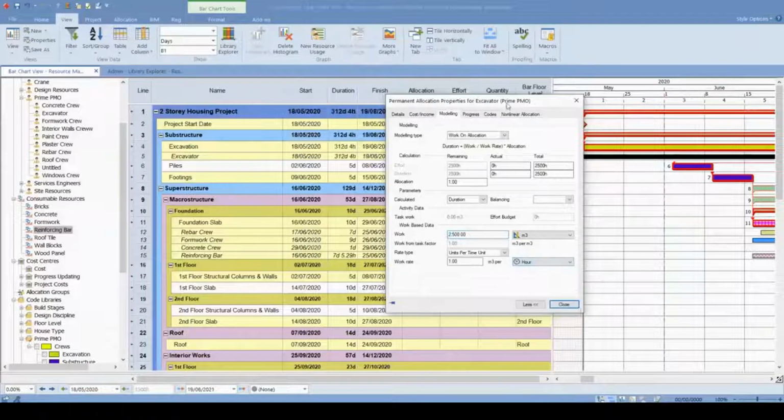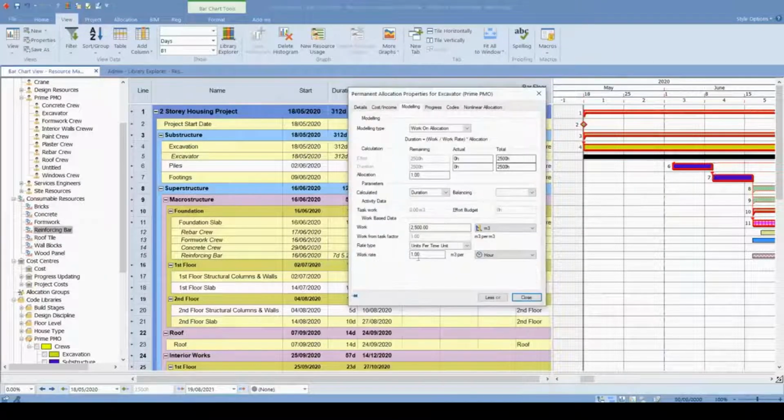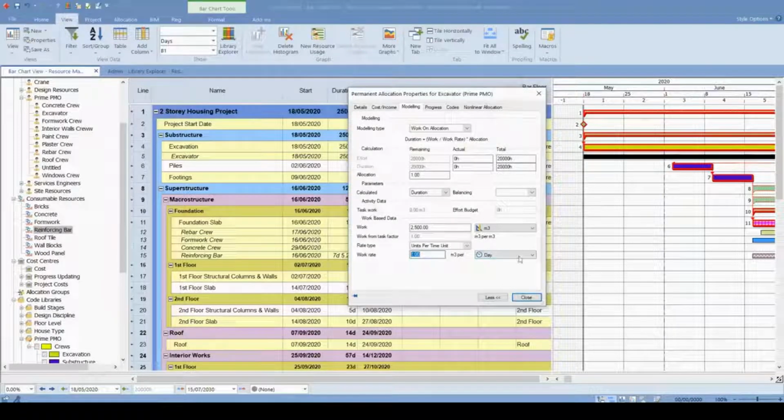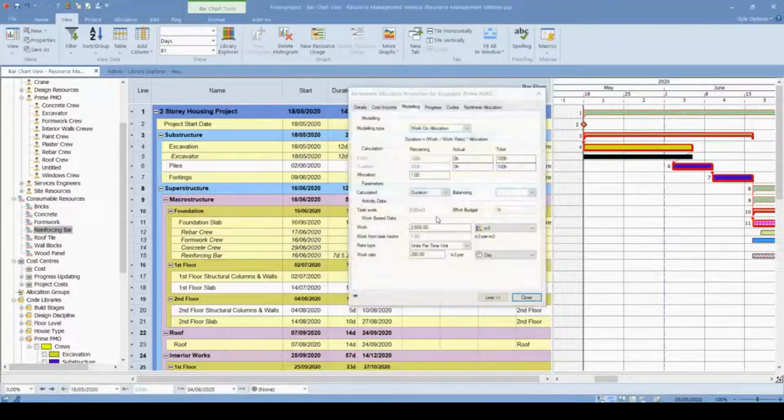2,500 meter cubes of excavation works we have. And you can see that the duration directly increased to an enormous number because Powerproject calculated the hourly work rate as 1 meter cube, which we need to adjust for time. And daily, if we know that we can excavate 200 meter cubes, you see that this activity will actually take 12 days. Initially, I had planned 10 days for this activity, but after using the model with the quantity, you can see that 12 days is going to be taken.